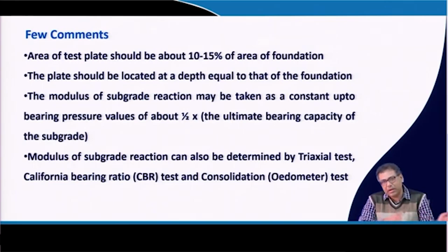Then plates should be located at a depth equal to the foundation. If not, then you have to apply the foundation depth corrections. Sometimes the depth correction is given for a surface plate, that means the plate load test is done on a surface. Okay, but sometimes it may be done at a certain depth that is less than the depth of the foundation. So, in that case also you have to apply the depth correction, but in that case the depth of foundation should be the difference between the depth of plate and depth of foundation.